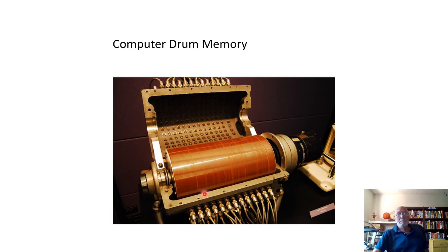Okay, here's the drum memory. Now the drum memory had different tracks, and it had sectors on each of those tracks, so many sectors. And in each sector, you would put an instruction, okay, for your program. And this is the one where you'd say, well, I don't want the next instruction to make me lose a revolution, okay? And a revolution was like 1.4 milliseconds. So you had to figure out the next instruction. If I had an address here, what was the instruction? How long is it going to take? Well, the next one I could put here. So I'd put it there.